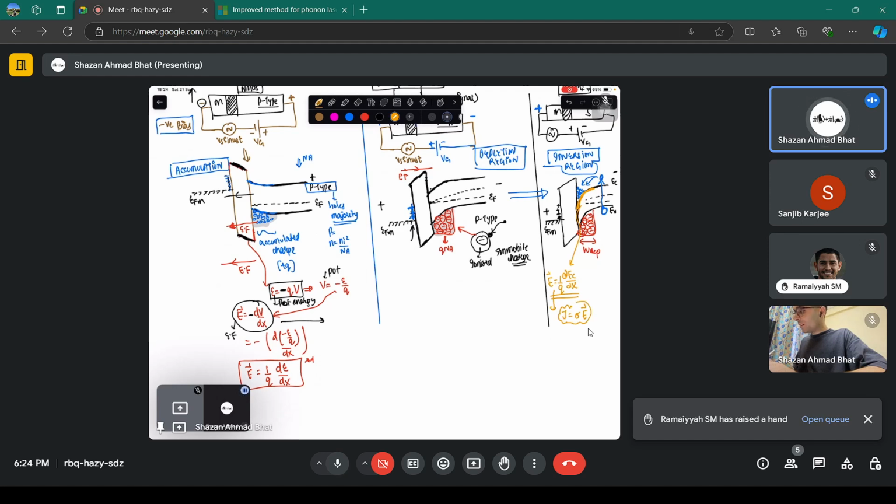That means there is actually the drift of electrons from the bulk towards the interface, towards the bent region, because an electron would like to go down the slope. Okay, there is the bend, and whatever electron gets generated here, it will like to go down the slope and get accumulated here. Because on the other end there are positive charges, it would like to stay there.